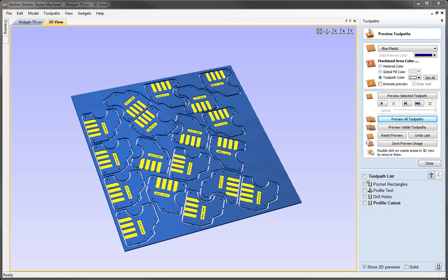Then we talked about the fact that if we wanted to, we could now create multiple copies of this, and this would be much easier to do because we'd done that association with the toolpaths using the vector selector to particular vectors on certain layers. So we went to the job setup, we increased the size of our job to our new sheet of material, and we used the true shape nesting to try different settings to optimize how many parts we could fit within that sheet.